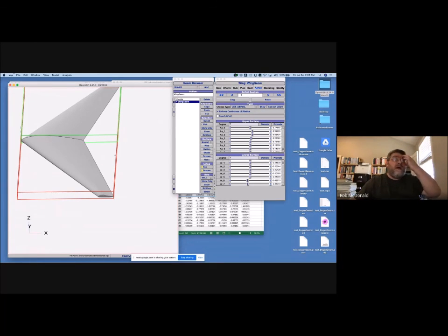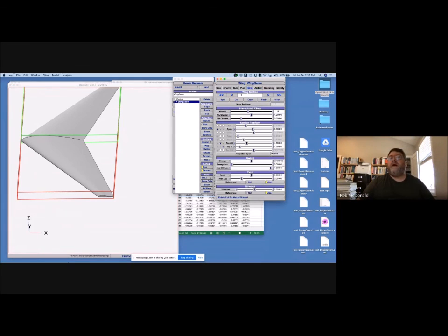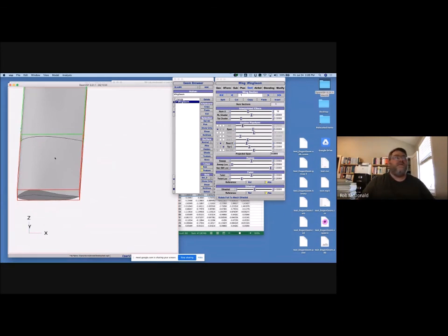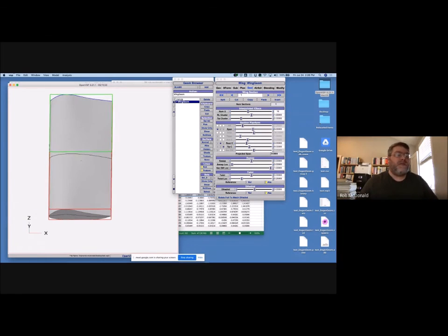But if you want to design a flying plank, a Hershey bar that flies, then there's no sweep. And the only way you can get that stability is out of the airfoil itself. And so if you have a flying plank, an unswept, Hershey bar kind of shape, then you absolutely have to have reflex airfoils in order for it to be stable.